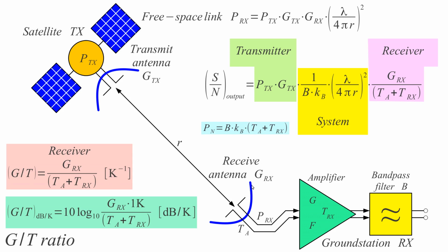What we do there is under illuminate the dish, so we get less gain because the dish is under illuminated, but we have much fewer side lobes pointing into the soil. We have these side lobes, but they are pointing into the cold sky, so that's not a problem. The side lobes of the spillover are those that collect lots of power.